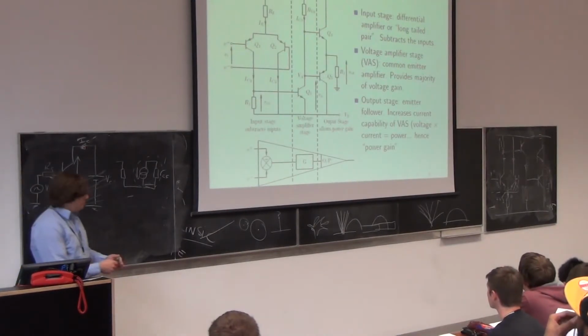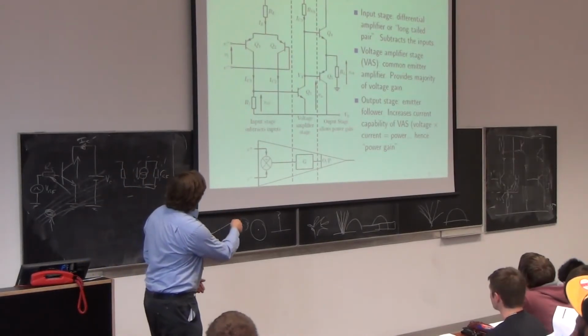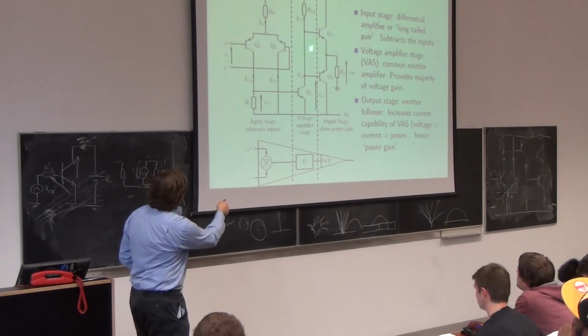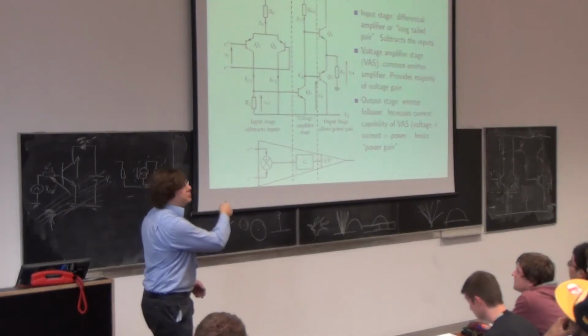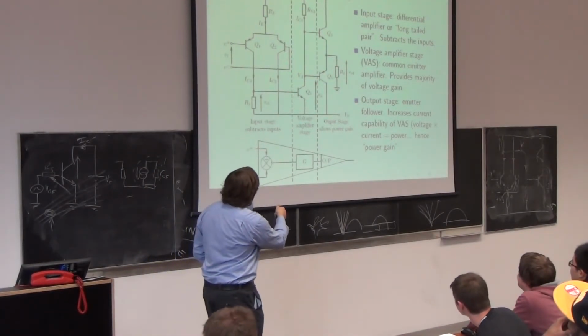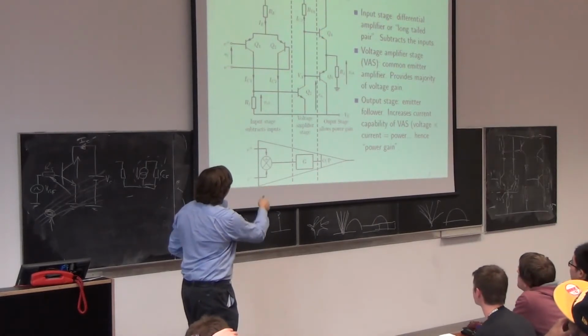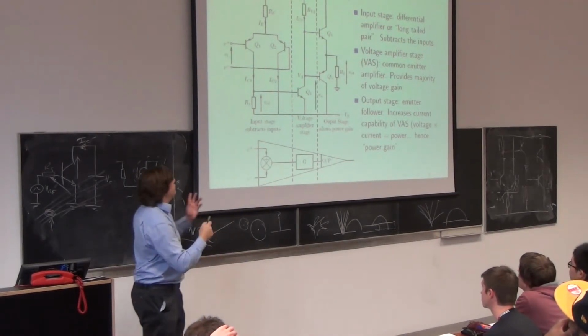So that's why I said we'll assume 0.7. Actually, that's a lie. And that's why you can't have a magic box here. We will eventually find a magic box to put there. But for now, no signal conditions, Q4, Q5, both switched off. No quiescent current at all.